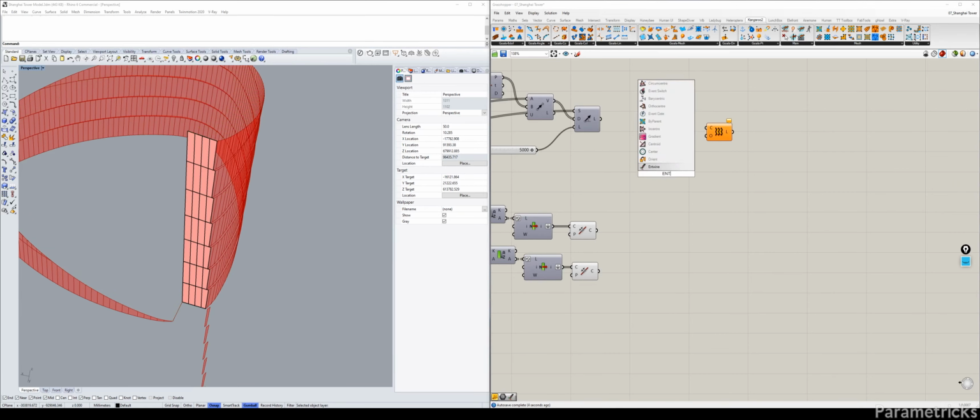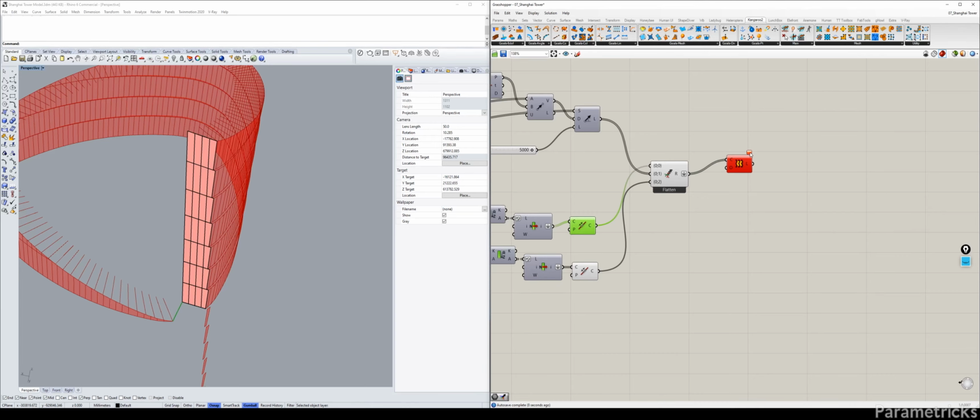But what I instead suggest is if we use an entwine, right? Where you can say, all right, the first one's going to go there, the second one's going to go here, and then the last, and then you flatten the output. Oh, you still don't get. Why is that actually? Loft cannot be constructed. Well, that doesn't really help me at all. But let me try to see, because I think it might have to do with that these are actually touching. But let me first check how the curve is orientated.